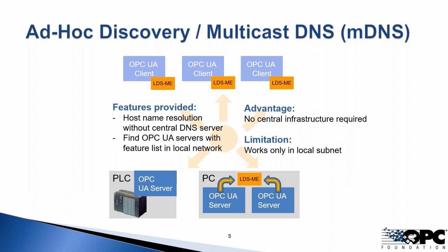So the first central concept we should talk about for OPC UA is the notion of discovery. Discovery allows one OPC UA application or component to discover other OPC UA components in the same system. Again, we use the notion of a system here to talk about the scope of discovery, and we're talking about, in this case, clients and servers discovering each other, or publishers discovering subscribers, or vice versa. The point here is that the concept of discovery is a global one.